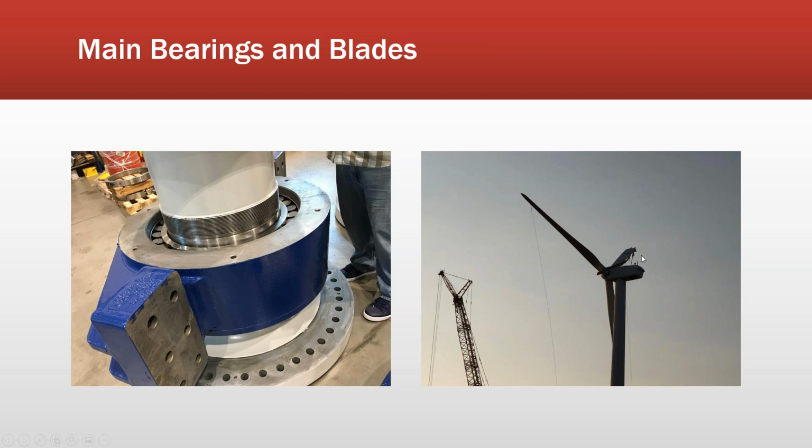We'd like to think we'd catch them a little ahead of that, but if we have certain types of defects in blades that cause an impulse, it's every time the blade passes the tower, there's an impulse that's seen through the entire train at the RPM of the blades. So that will show up in the signature. If we see a peak, because they'll normally be averaged out by the software, if they show up as a peak, then we know that there's a condition that needs to be evaluated.